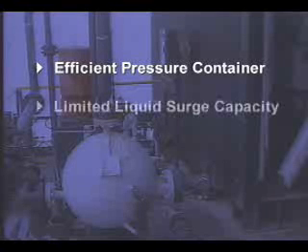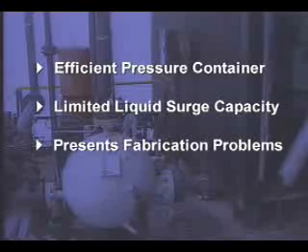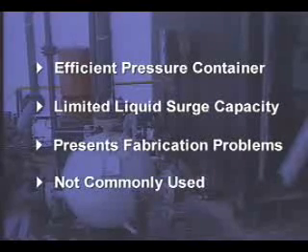Spherical separators are efficient pressure containers, but they have very limited liquid surge capacity and can be difficult to fabricate. For these reasons, they are not commonly used.